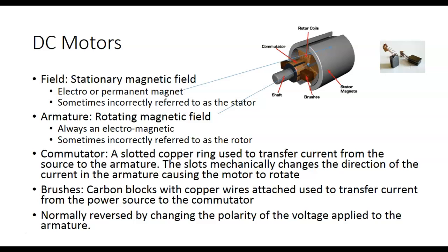With permanent magnet motors, we can't change the torque on them. But these are the cheapest. These are going to be the fractional horsepower motors. Except for the stepping motor, this is what runs all the motors on our lines over there. This is what's in your car. Every motor in your car but the starter; your starter is not a permanent magnet motor. So the motor that runs your windshield wipers is a permanent magnet motor.